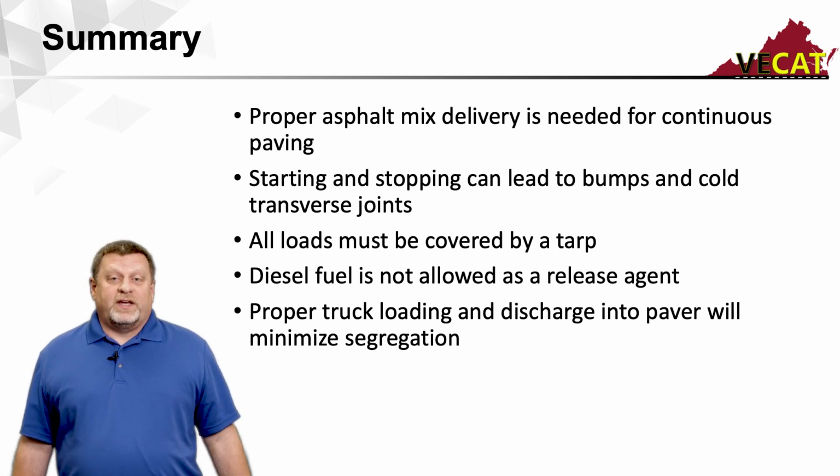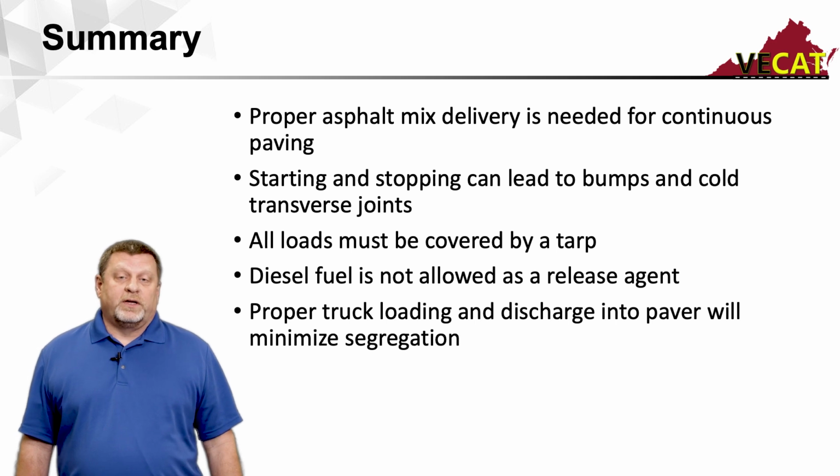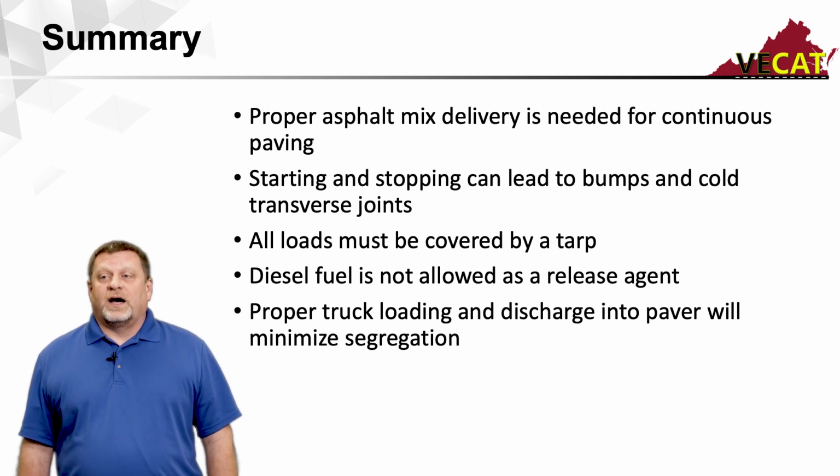It's a requirement by VDOT, and it's also a benefit for the mix. That tarp does provide a layer of insulation and allows the cooling air to pass across the mix without making direct contact. So it's important that all loads are tarped. We talked about diesel fuel is not allowed as a release agent. VDOT has an approved list. You can find it online, but it's important that any release agent we use be an approved product from VDOT.